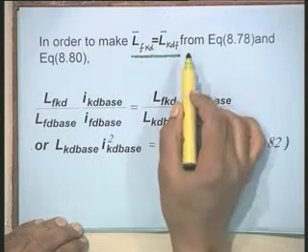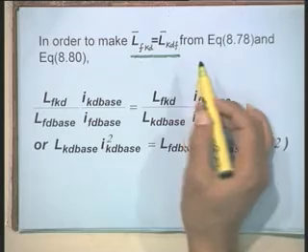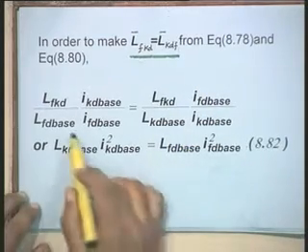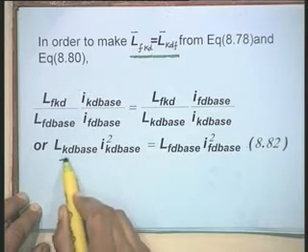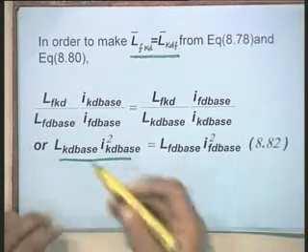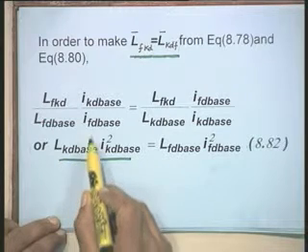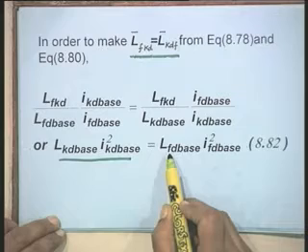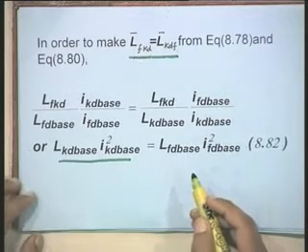Now, this is by definition which we defined when we wrote the flux linkage equations in the rotor circuit. Now, when we equate these two, okay, we will get this expression, just cross multiply, we will find that it becomes LKD base into IKD base square equal to LFD base IFD base square. You can just check it, it comes out to be like this.